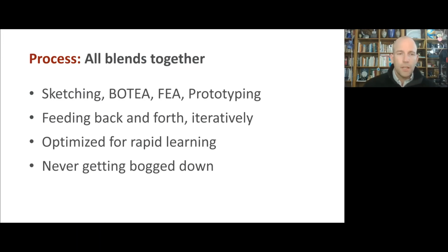You have to sketch and then do some back of the envelope analysis and learn from that and say, oh, well, this is a problem, or, oh, this implies I should eliminate this thing, or make this thing really small, or make this thing really big. And doing the finite element analysis, just a quick version, really helps in making sure that I'm not missing big things in the back of the envelope analysis. And same with prototyping, with low fidelity prototypes early on. That's super helpful.